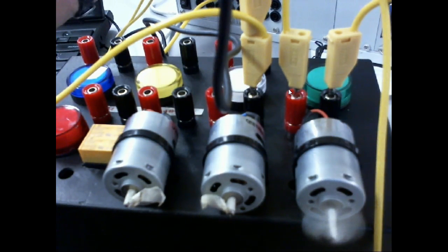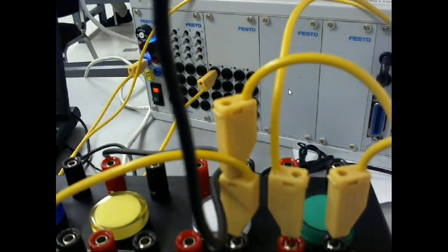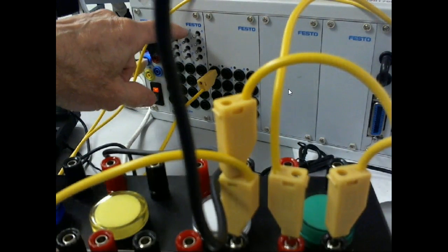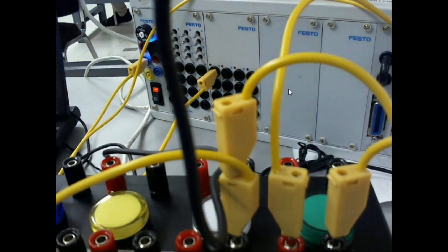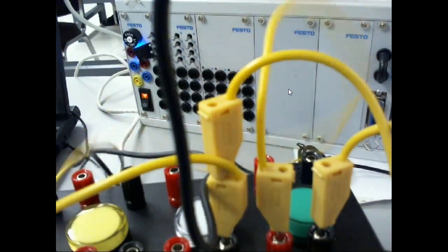And here's my stop button. And it's momentary, right? I understand that. But the problem is, I don't know if y'all are looking, since I'm using an examine if open, I have to use a normally open switch for my stop button. Well, okay. So I'm going to disconnect the outputs because I don't have enough room over here.